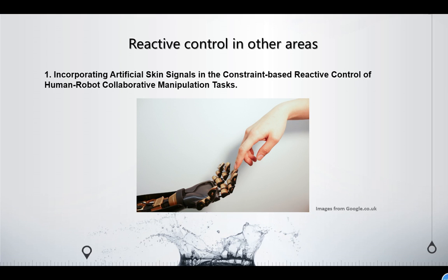The robot controllers detect and avoid collisions based on information from artificial skins. In order to reduce the amount of data, the discrete optimization algorithm selects the maximum number of cells according to the signal intensity and spatial distribution of activated cells.